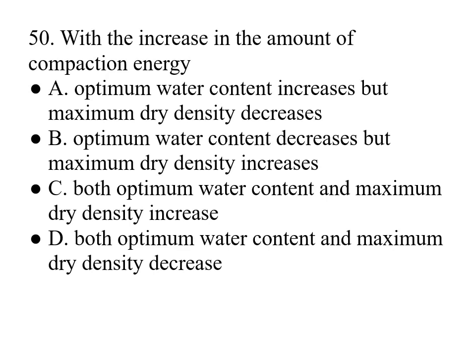50th question. With the increase in the amount of compaction energy, the optimum water content decreases, but maximum dry density increases. So the option is B.